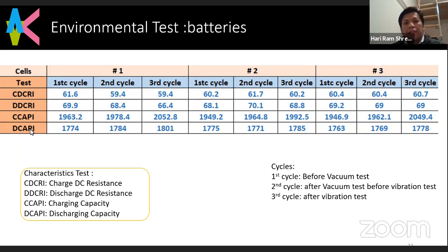After that, the physical inspection is an important part of choosing the battery for cell matching, because in our case, the battery is 3 series, 2 parallel. We need to use batteries with very similar DC resistance or DC impedance. In the series case, the batteries would not balance each other, so a battery could burn or produce heat. It will not be good for the CubeSat purpose. So after the environmental test, we need to choose carefully batteries with very close DC resistance values for this battery construction.